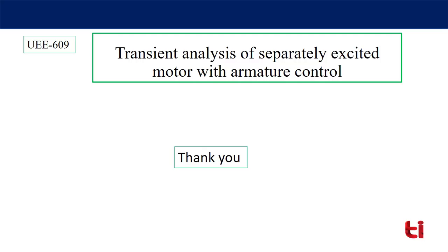So today we have discussed transient analysis of the separately excited motor. We have modeled the complete drive system based on KVL equations and found that linear differential equations can be solved to find current and torque of the system, and from there we can obtain the time required for these transient conditions to die out during starting, braking, plugging, etc.